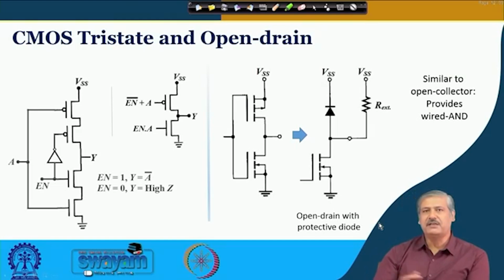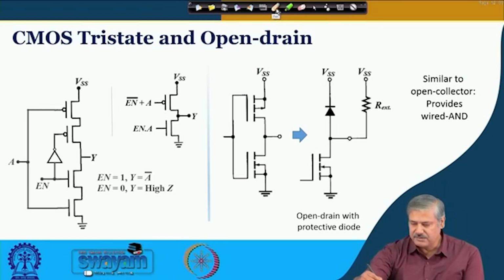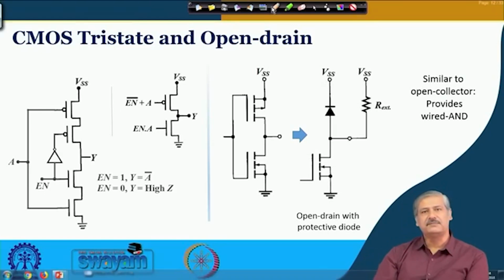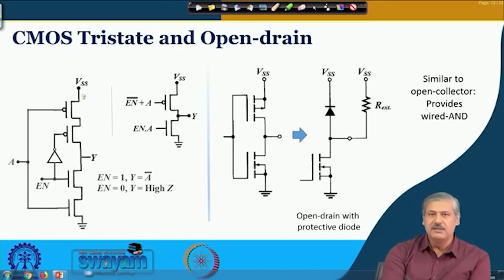Now, if you take this a bit further, in the left hand side what you see is a circuit, right, where the NMOS and NMOS over here is in series with two PMOS that you see. They are not in parallel. If they are in parallel, then there would have been a NAND logic forming. The other thing that you see here, at this input between them there is an inverter present.